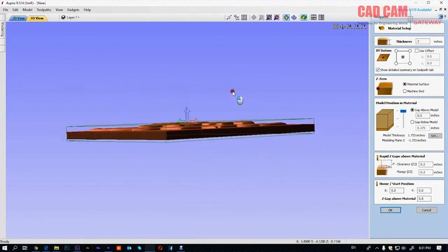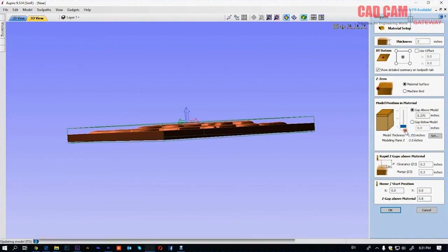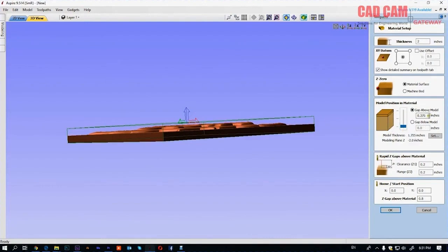As soon as I increased it, notice here that it added a little thickness below in this color. See here, it added the thickness properly. So you can also adjust it from here like this. Now what it did was add some thickness on top and some below. It's better to add a little thickness on top so that it gets removed during cutting and we won't have any problem with it. I set it to the level at the bottom and added a little on the upper side.